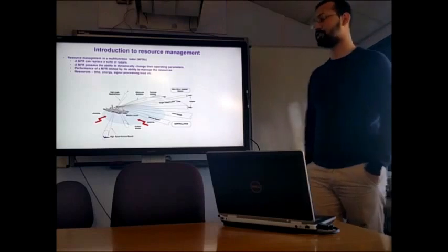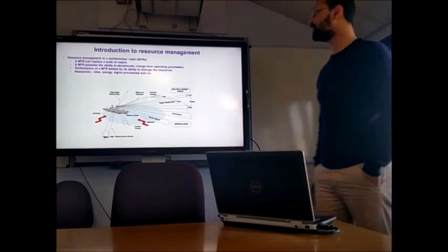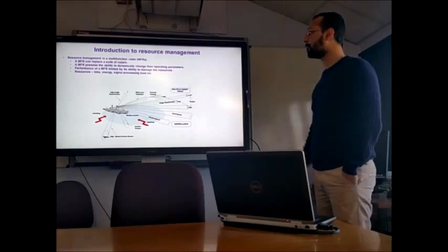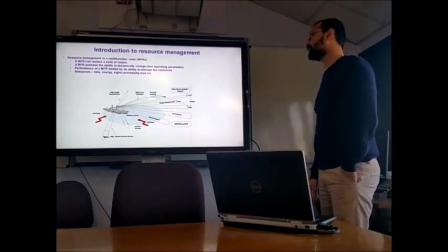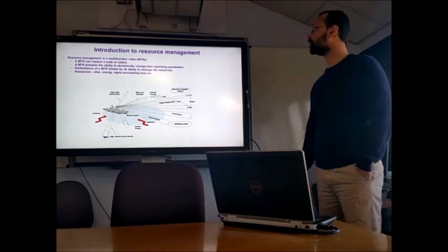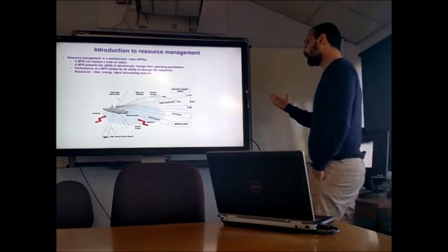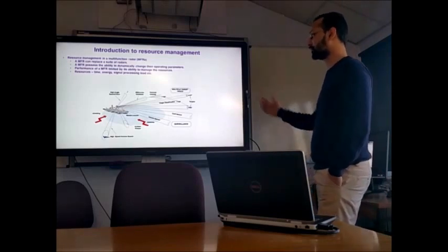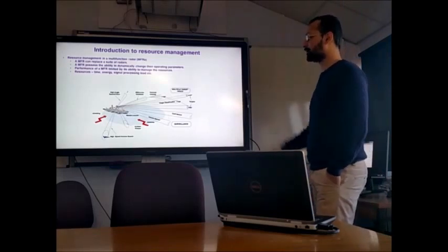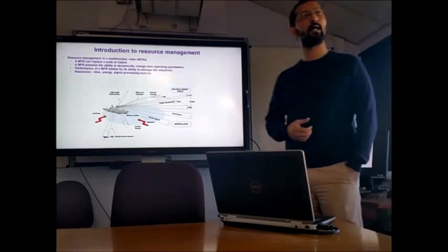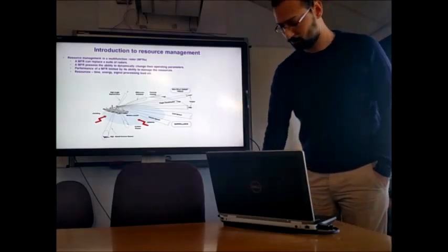One of the challenges is how do we distribute resources such that we can carry out all these tasks in the most optimal manner. And also, a multifunction radar possesses the ability to dynamically change its operating parameters. So, for example, if it was spending too much resource, such as dwell time, on tracking targets, in order to be able to carry out surveillance, it can modify its parameters such that it can get a global optimal performance out of all the functions.